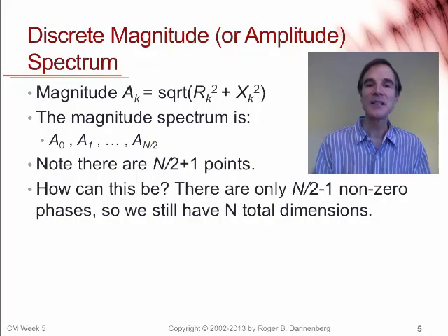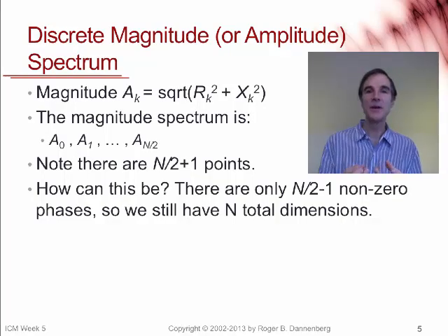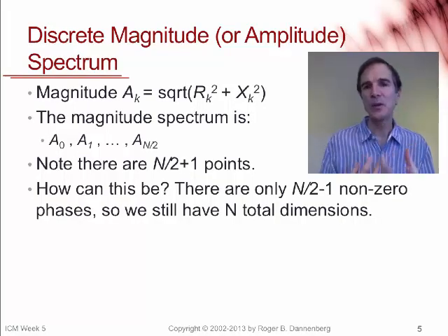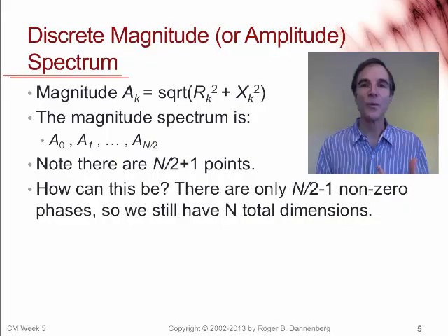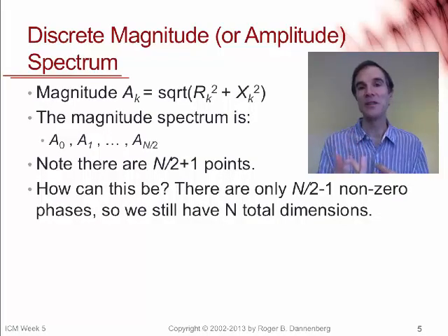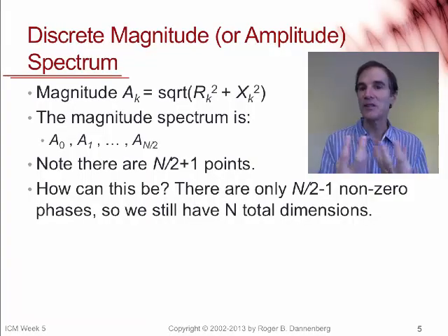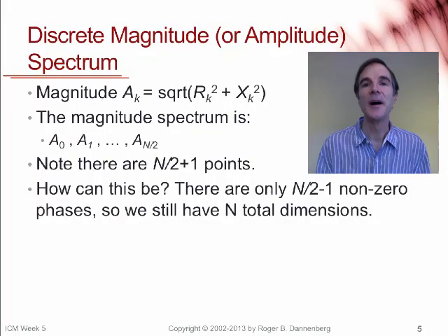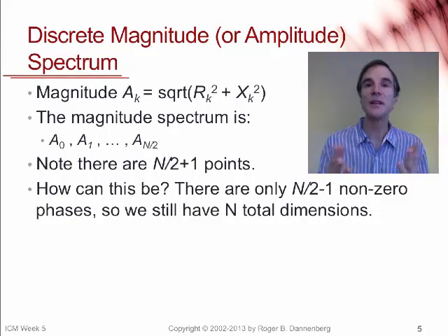Now, the next thing to look at is when we're doing spectral analysis, usually we're not actually interested in the real or the cosine part versus the sine part. These are the same frequencies, just calculated with different phases. And so what we really are interested in is, let's throw out the phase and just see what would be the amplitude if we added those signals together.